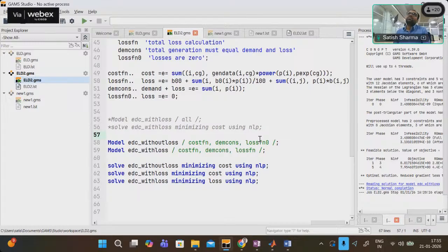So it can basically minimize the imbalance. Certain deviation is allowed as per the regulations. Different countries have different regulations and different allowed ranges, like plus minus 5% or 10% is allowed, but more than that you have to face penalties. So yes, if you want to do ELD with renewables, and a renewable power production company is certain that this much power output can be maintained, yes, we can do economic load dispatch. And if it cannot commit, because it is highly uncertain, then we do not prefer that.